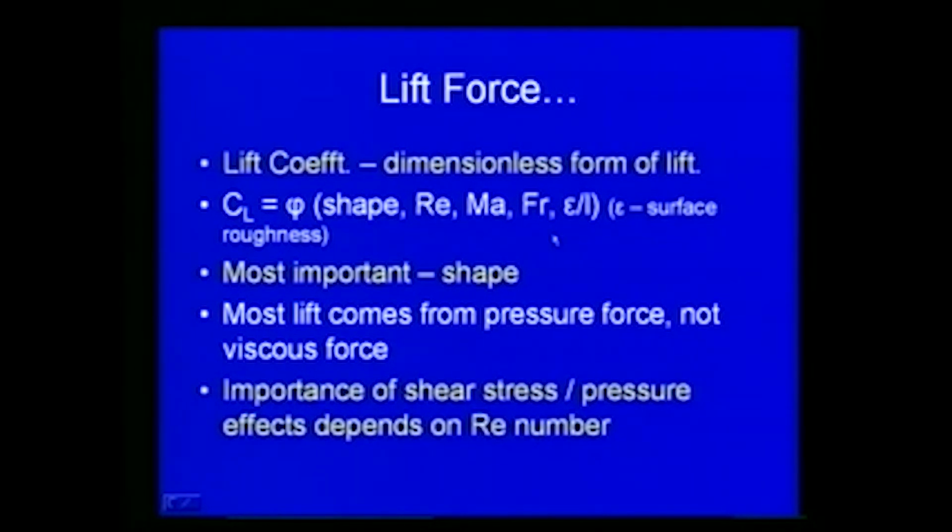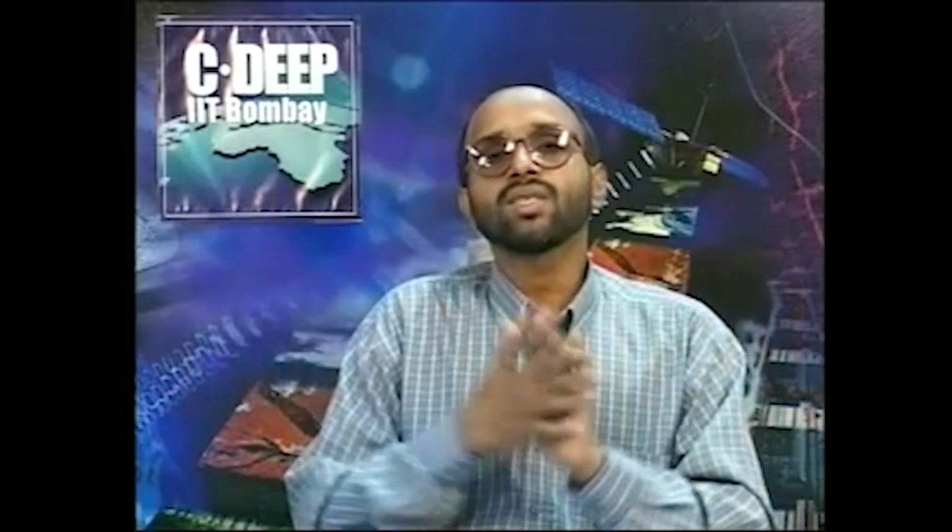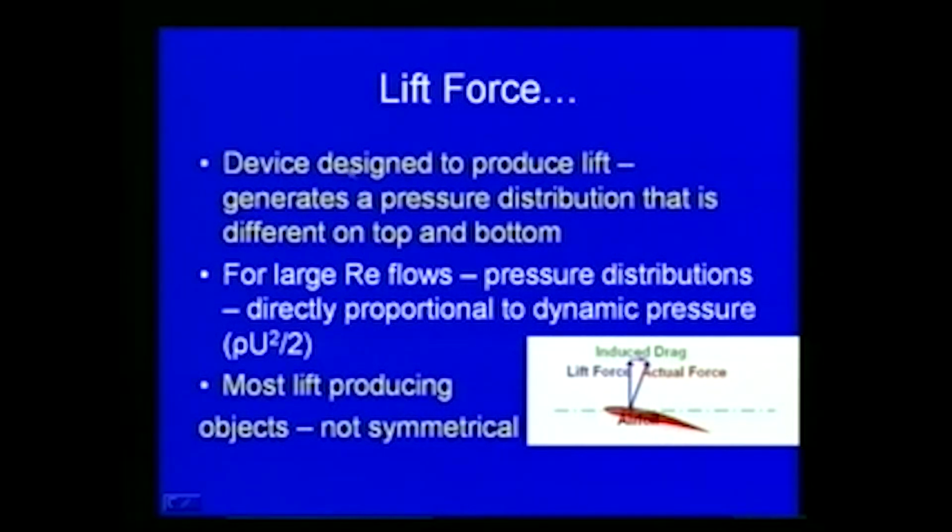As we have seen in the case of drag force or drag coefficient, the effect is small, but the Reynolds number is another important parameter here. Depending upon whether the flow is laminar or turbulent, or when the Reynolds number is increasing or decreasing, we can see that the lift force changes. Now, as far as lift force is concerned, we can design devices to produce lift, as we have seen in the case of an aircraft, so that a pressure distribution that is different on top and bottom is generated.